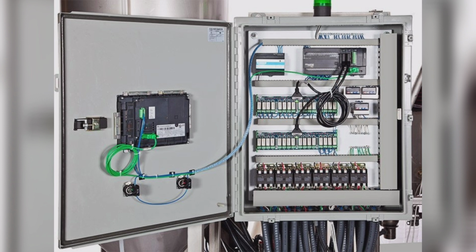In this way, the PLC will monitor and control the system as well. Then what are relays and contactors? The PLC output will be wired to the bank of relays. Then it will close the terminal contacts and send power out to turn on and off the devices on the assembly line. Smaller relays will control devices such as lights or fans, while the bigger relays, called contactors, are used to control the motors.